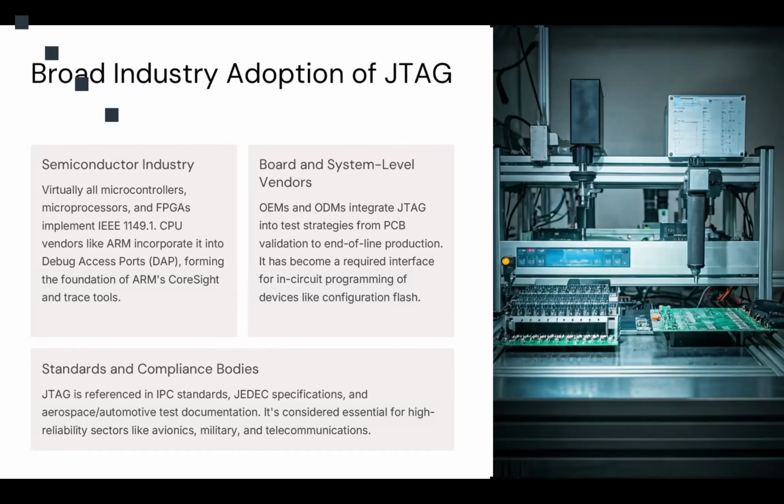We also saw an interest in JTAG testing from board and system level vendors. So it's not just semiconductor, chip, microprocessor or microcontroller makers. The original equipment manufacturers and original design manufacturers also integrated JTAG into their board level validation and testing, because JTAG gives them the ability to have an automated board level testing configuration.